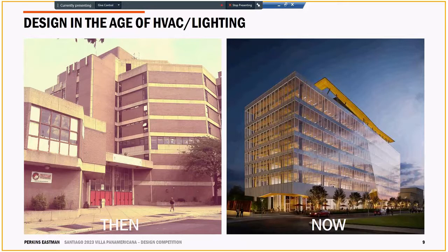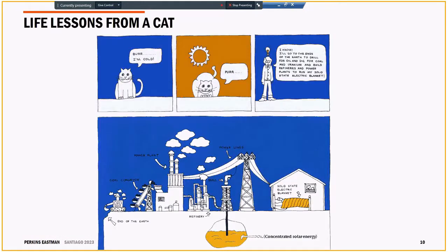Simply because glass is not a very good insulator, and we're having to deal with creating comfort at a much higher level because of the poor insulation that glass offers. So obviously this is an extreme, and what we would be looking for in applying passive design strategies in this day and age is to not take it to that extreme.